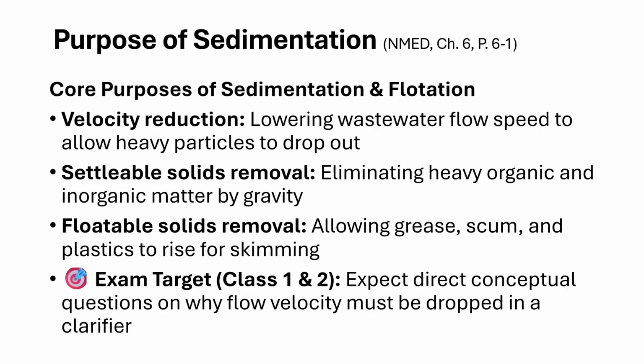But for class 1 and 2 or levels 1 and 2, expect conceptual questions on why we have to drop the velocity in that clarifier. And again, what we're doing is slowing down that flow velocity so the heavier organic and inorganic settle out and the lighter material rises. That's why we're slowing it down. We're giving that mechanism some time, detention time, so those 2 processes of sedimentation and flotation take place.